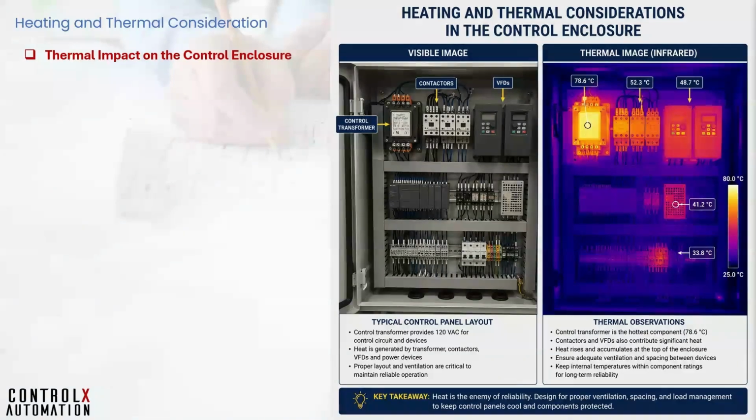What is the thermal impact of all heat sources inside the enclosure? Other than the transformer, we may have other components like VFDs, power supplies, motor starters, etc., which all contribute to the overall heat production inside the enclosure, and their thermal impact must be accounted for. To estimate the temperature rise inside a painted steel enclosure without forced ventilation, determine the total surface area exposed to air using the enclosure dimensions.